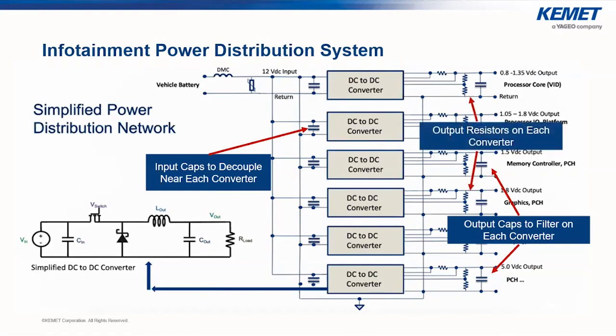We also need to monitor the voltage. These DC to DC converters are closed loop systems, and for closed loop systems to operate, you need information related to the output, which in this case is the voltage. You need to feed that back into the functional block so that the control loop can make adjustments to compensate if the output is varying beyond the set limits. Typically a voltage divider using some precision resistors is used. We take the output voltage, run it through two resistors, tap off the middle node and feed that back into the DC to DC converter. So now we have a feedback loop of a fraction of the output voltage.